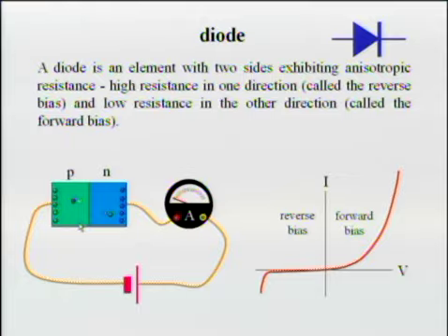Depending on the application of the diode, we want this current to be as small as possible. But we even have a diode which is referred to as an avalanche diode or Zener diode, in which we take advantage that eventually, if the field is sufficiently strong, those minority carriers can acquire such speed in their materials that they will knock out more carriers.